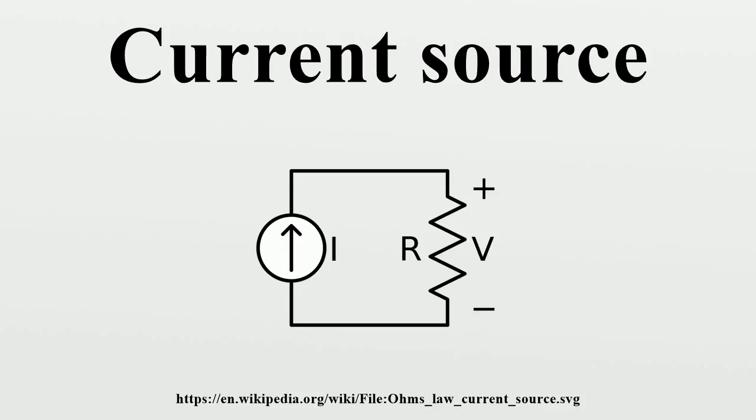The emitter current of Q1, which is also the current through R2, is given by IE = (VZ - VBE)/R2. Since VZ is constant and VBE is also constant for a given temperature, it follows that VR2 is constant and hence IE is also constant. Due to transistor action, emitter current IE is very nearly equal to the collector current IC of the transistor. Thus, the load current is constant and the circuit operates as a constant current source.